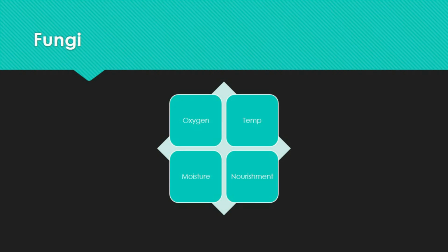The consequence of decay in both circumstances is the disappearance of sound sections of the wood, lowering the wood's initial load-bearing capability. From the first admission of the hyphae into the wood cell to the ultimate disintegration of the wood itself, decay includes all stages of infection on the pole. While severe degradation is apparent to the human eye, the early incipient phases of this type of decay are actually not. The principal decay fungi that infect softwoods are what we call the brown rot fungi.